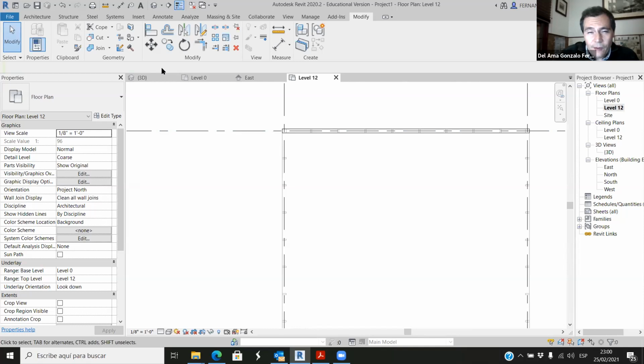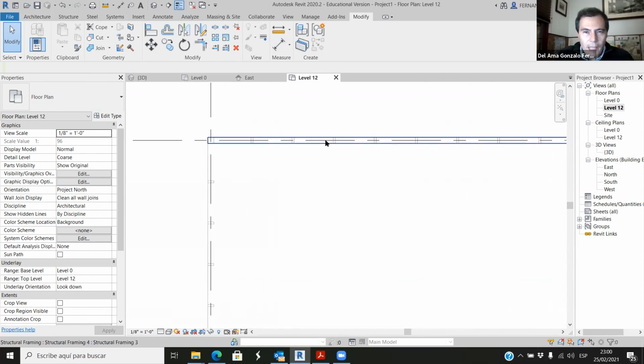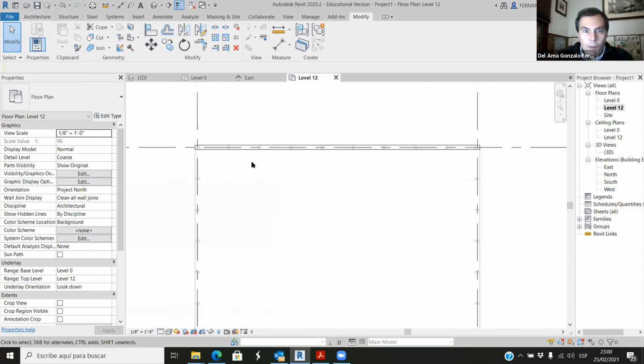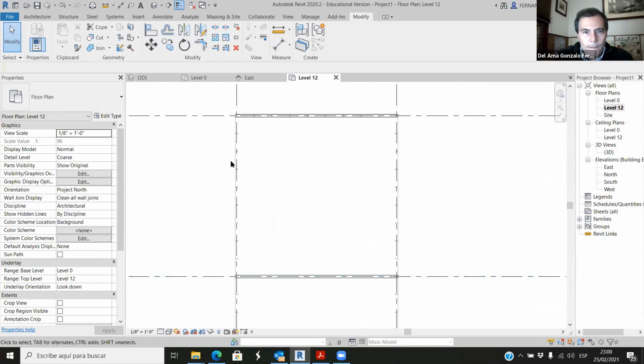This is very useful because there are things in Revit that we cannot make with the walls or the elements that we have here as families, and we have to create our own component. So if you become familiar with this, it's great, because at least when I'm doing this, I use this architectural component model in place many times. I find it quite useful.